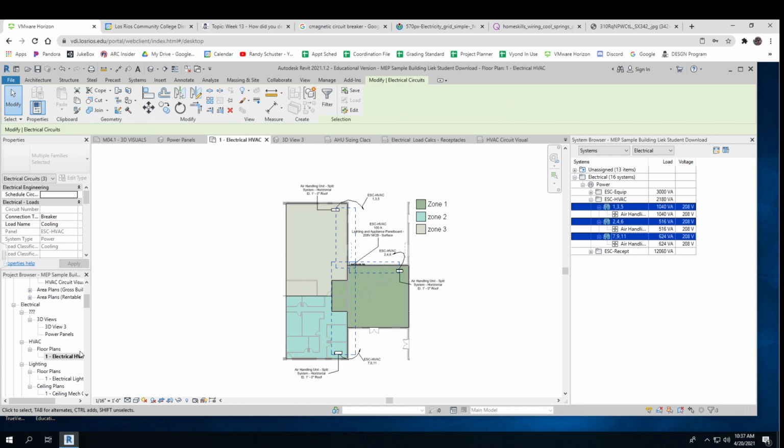I took a snip and I put it onto a drafting view because it really does show that. And when you do that for each one of your receptacle zones, it really looks cool. So you can have each one of these circuits or a few of these circuits in each visualization to show. And that makes a really nice visual without gooping up a drawing.